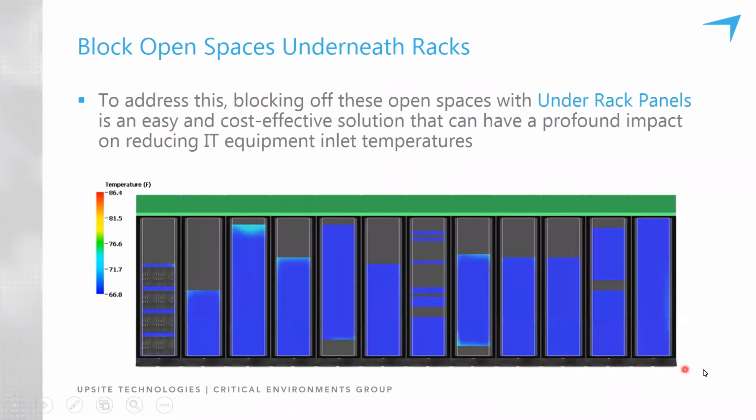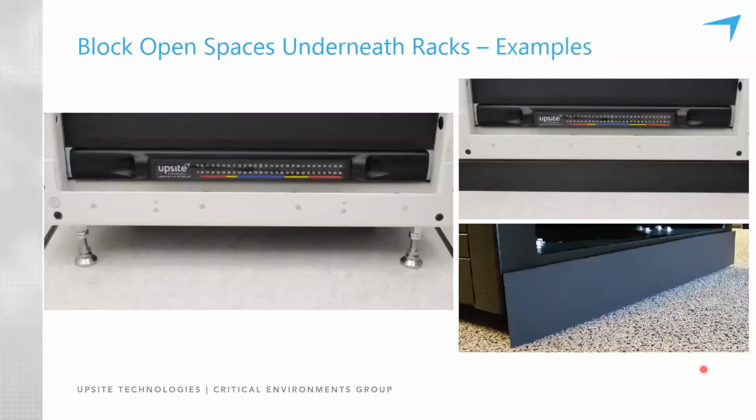And these images are the result of detailed CFD analysis of a computer room. And there's a direct relationship between the evenness of intake temperatures and the efficiency of the room. The goal is always to get intake temperatures into all of the IT equipment, every single U, as even as possible. And that will directly relate to how efficient the room can become. So let's take a look at a couple of images of what these actually look like.